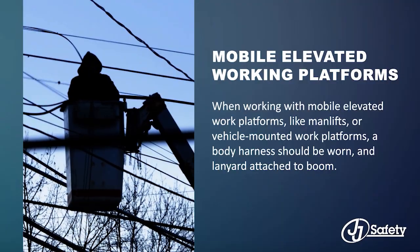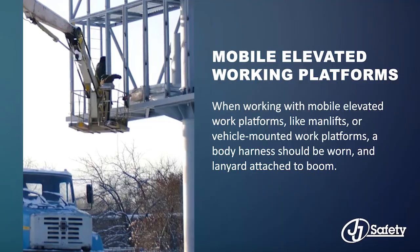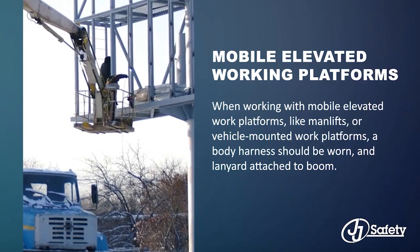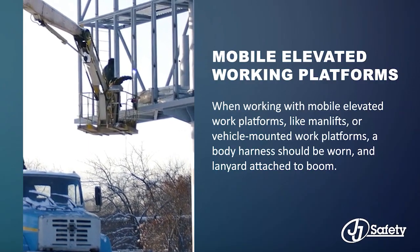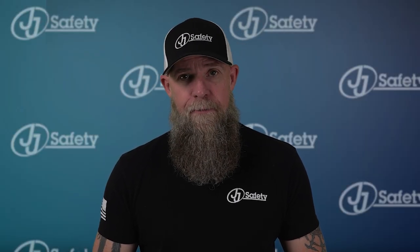When working with mobile elevated work platforms like man lifts or vehicle-mounted work platforms, body harnesses should be worn and the lanyard should be attached to the boom or basket. Engineered lifelines are fall protection systems that allow workers to move safely on elevated surfaces.